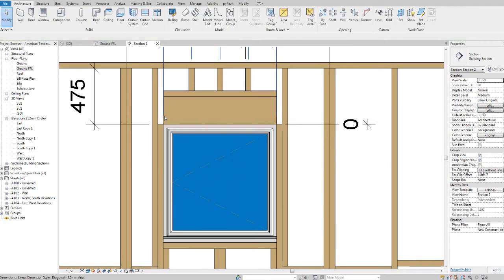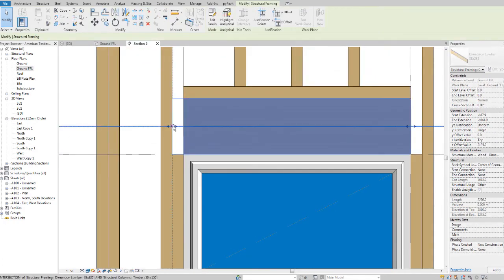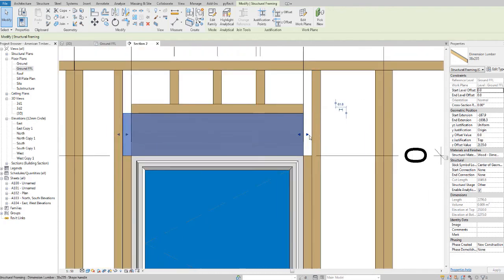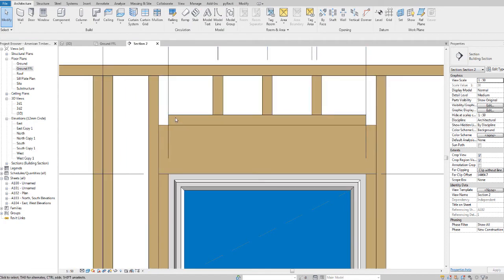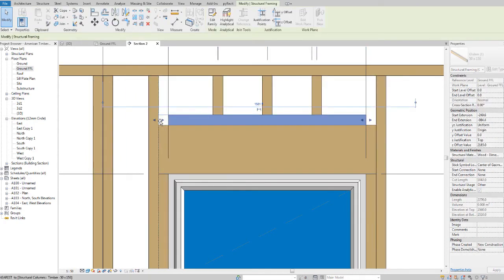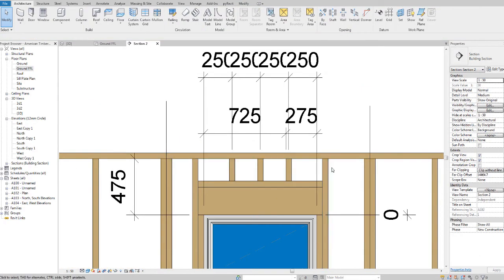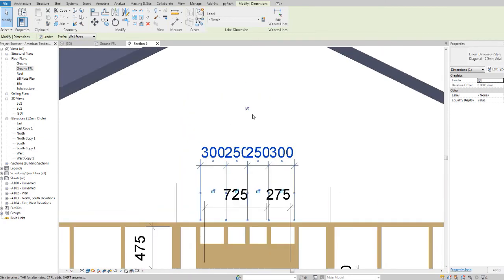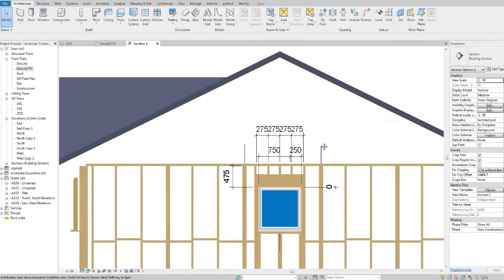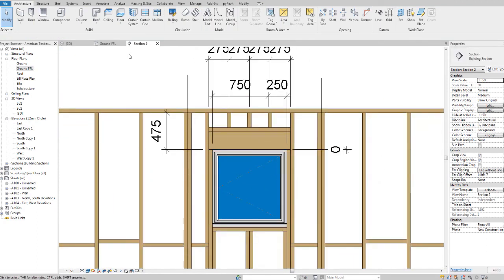And then these lintels have to be supported on top of these studs. This is the correct way to structurally support them. And I'll just equalize these again by just redimensioning it to here and here, and hit equalize. There it is. Of course I have to sort out the lintels at the back, but I just had to mention that.